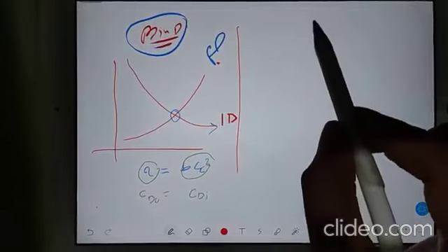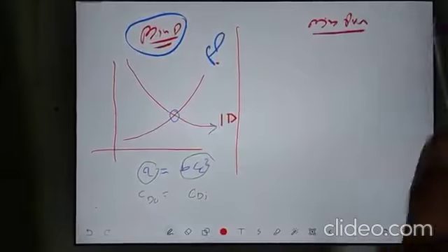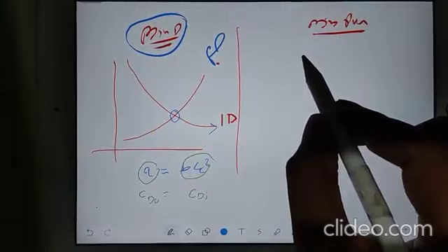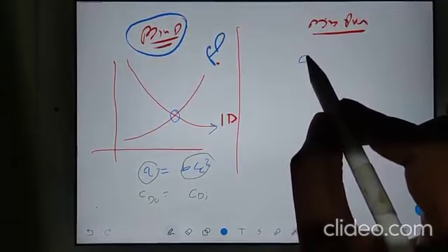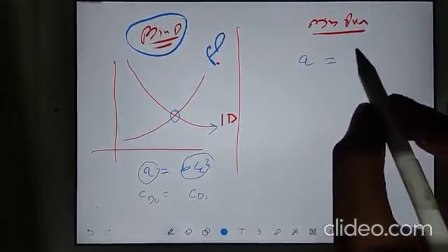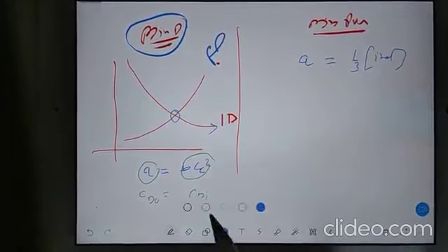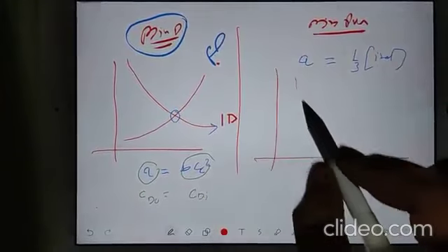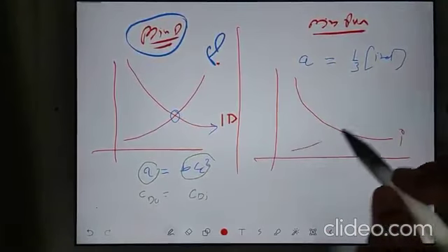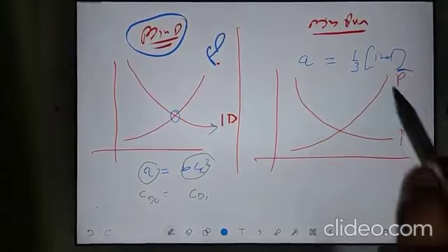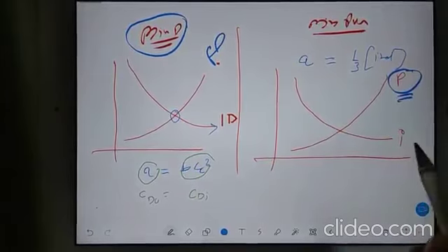But if you talk about the minimum power condition, then according to mathematics, your parasite drag, or you can say your profile drag, is equal to 1/3 times the induced drag. Now you see, in the same diagram I will draw, this will be the induced drag and this will be the parasite drag. So where is the coordinate where parasite drag is 1/3 of induced drag?